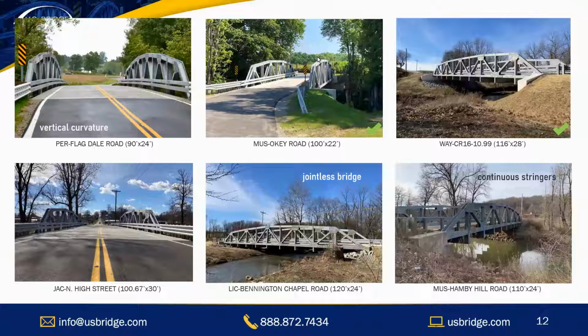And on the far right, at the bottom, is Muskingum County's Hamby Hill Road. The unique feature there that is worth mentioning is we had staggered continuous stringers over multiple spans, 2 or 3 spans across their floor beams to match criteria with the panel spacing, which was under 14 feet, which allowed us to decategorize those floor beams from being fracture critical, which is an important feature to mention.